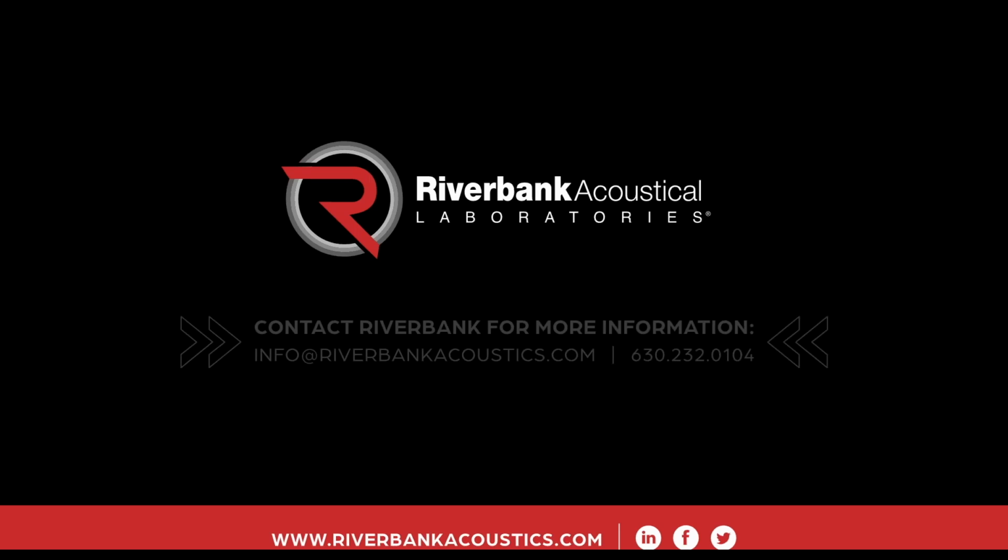But I think what you might be asking, or alternatively, you might be asking if that same wall panel, rather than being flat on the floor directly, was tested upright or vertically, how would that affect the performance? Well, in terms of Sabins, or total square feet of sound absorption produced, you're going to see a reduction in sound absorption at low frequencies and a boost in absorption at high frequencies.